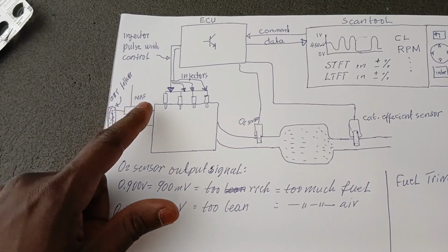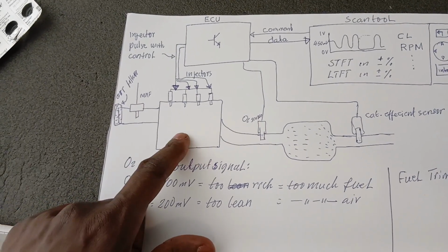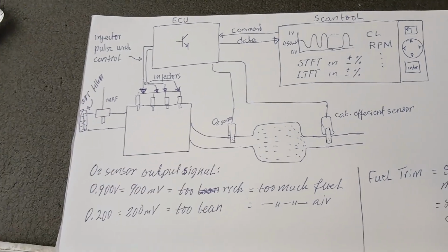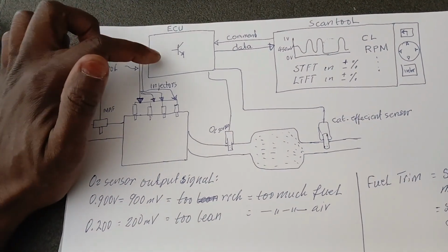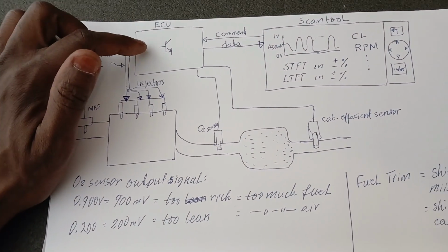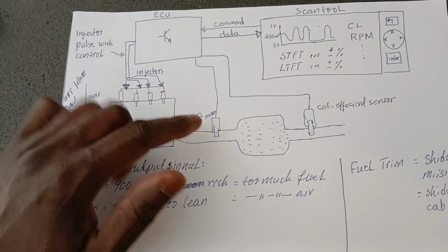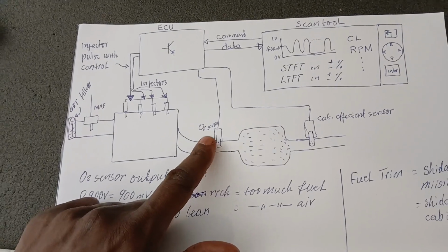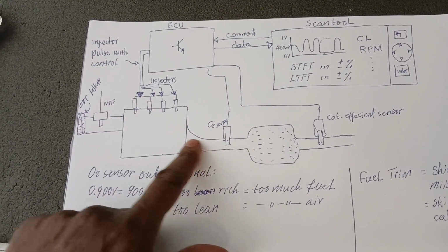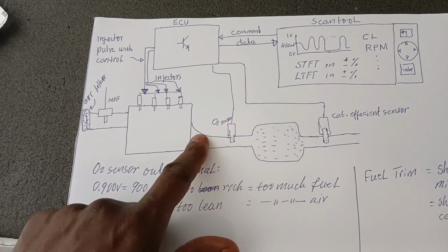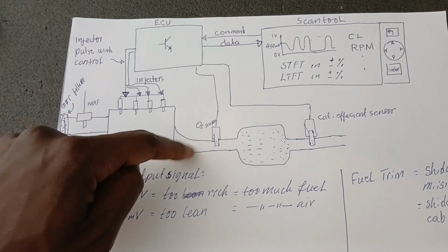That is, if there is no vacuum leak and the fuel pump, of course, has the right pressure. For all of those things to happen in a harmonious way, it is the ECU which makes it possible. It gets data or voltage changes from the O2 sensor to measure how much oxygen is in the exhaust and tell the computer if there is too much oxygen in the exhaust.